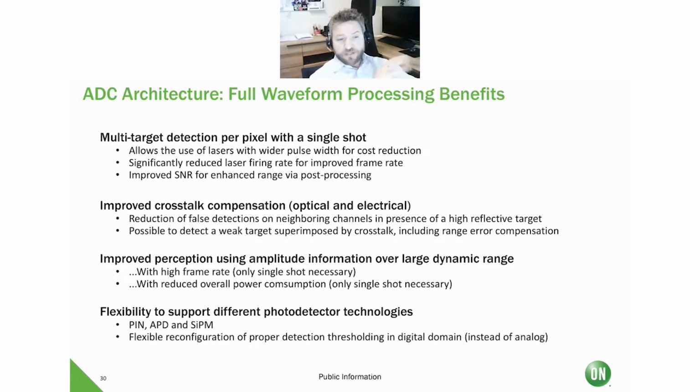So we are compatible with PIN, APDs, and, what we will also demonstrate in this webinar, with an SiPM. Because we have full waveform processing, we are not thresholding in the analog domain like with the TDC approach. We are thresholding whether there was a detection in the digital domain, and this gives us additional flexibility in adjusting to different LiDAR system environments.